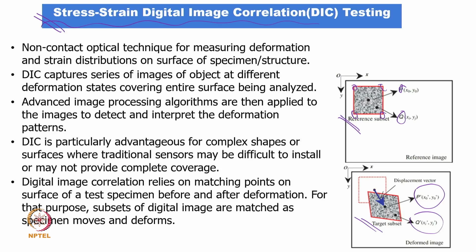I believe there is a lot of future for this technique. So, what we can say is that it is non-destructive and optical, because we are capturing images for measuring the deformation and strain distribution on the surface of the specimen and structure. Again, this is a surface analysis, not a subsurface one, because for the subsurface we will not be able to capture images or see the deformation. However, if some subsurface failure leaves an impression on the surface, it can be captured; otherwise this technique is only for the surface.